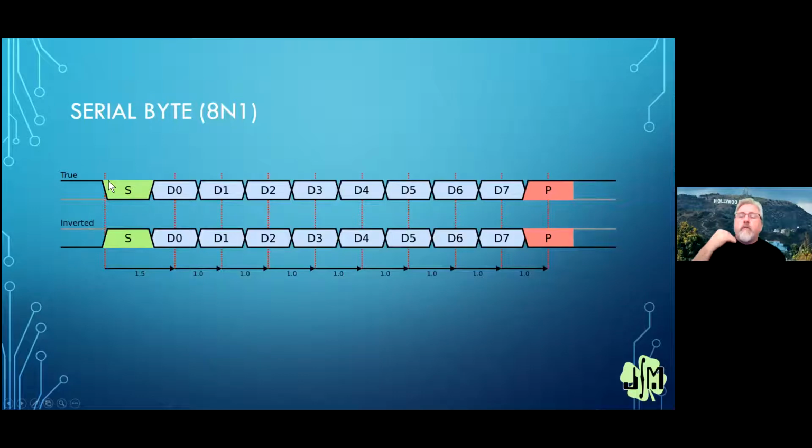And then when we want to transmit a byte, it's actually very easy. Because we know what the baud rate is, we know how long each bit is. And even if we're synthesizing that in code with the Propeller, it's very easy because we can look up the clock frequency, there's an instruction for it, and divide that by the baud rate. That will take us from our system clock, which is in ticks per second, to ticks per bit. And we can use that as a timer.